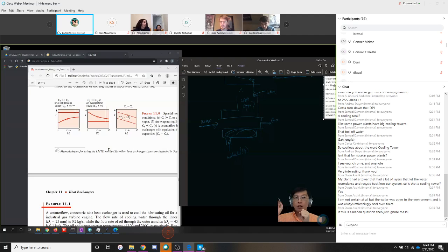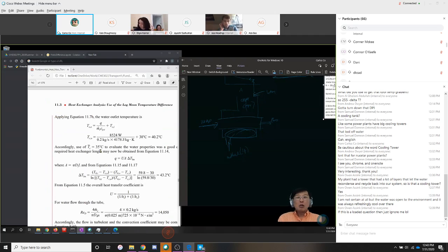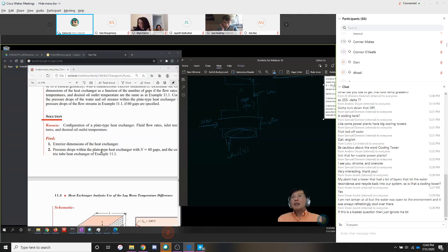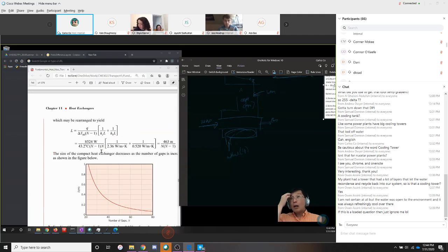If you know the LMTD, the log mean temperature difference, you're able to get the amount of heat that gets transferred. But if you think about it the other way around, in which I say I need to transfer so much heat, and this is the area, this is the heat transfer coefficient, tell me the temperatures. Notice that in that expression you have that logarithm, so it's a somewhat more nonlinear equation that you need to solve. It's not that difficult.